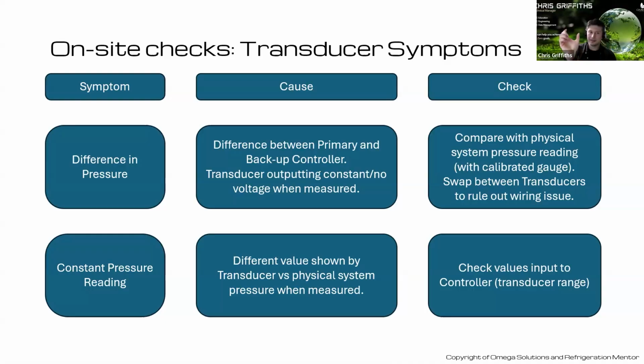You'd think it would occur to you when it's a consistent 28 bar at all times for a week. That system's working really well. Consistent suction pressure. No, it's because it's not reading correctly. So that's one of the things we can check, if it's a transducer.